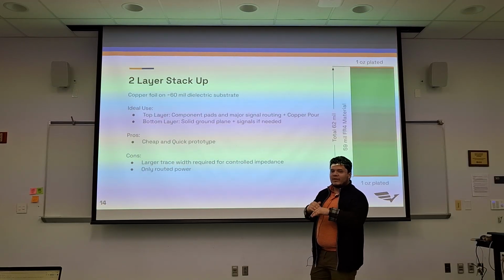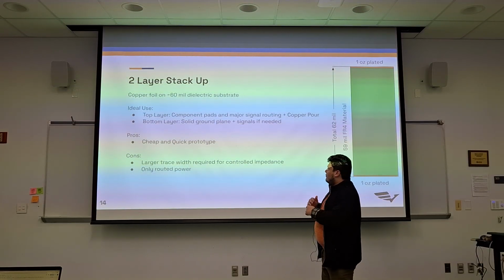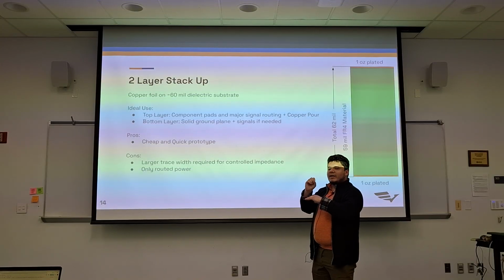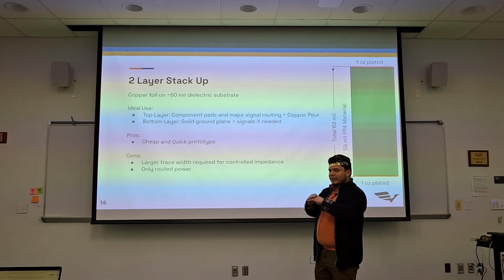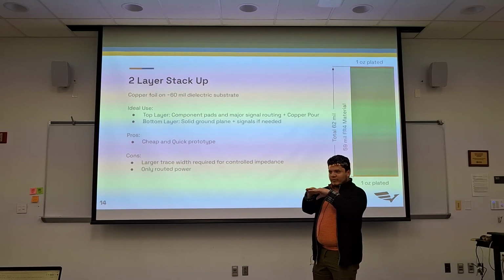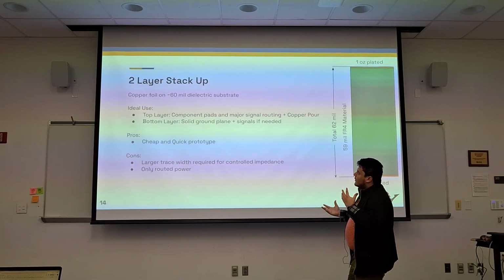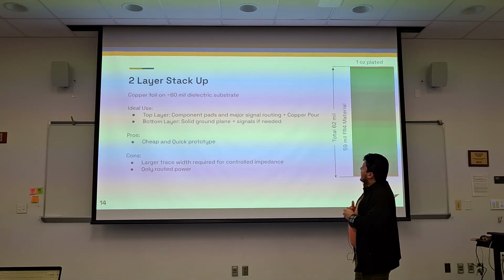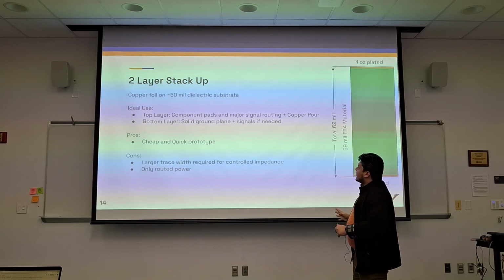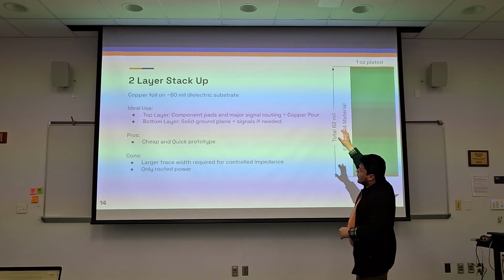They're never going to be thicker or less thick. But since we're plating over, so we're adding or depositing extra material to try to match that, that can be plus or minus some sort of tolerance, right? So they're going to try to be as close as possible always, but it's always a risk. And so ideally, in this case, for a nice solid 2-layer stack up, we're going to have all of our signals on 1 layer.